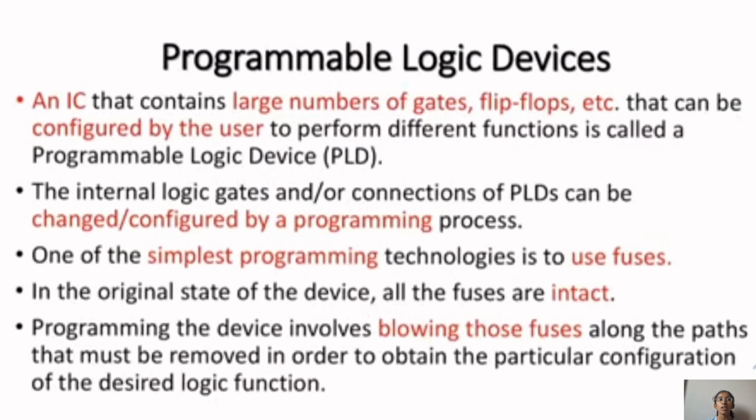One of the simplest programming technologies is to use a fuse. In the original state of the device, all the fuses are intact. Programming the device involves blowing the fuses along the paths that must be removed in order to obtain a particular configuration of the desired logic function.